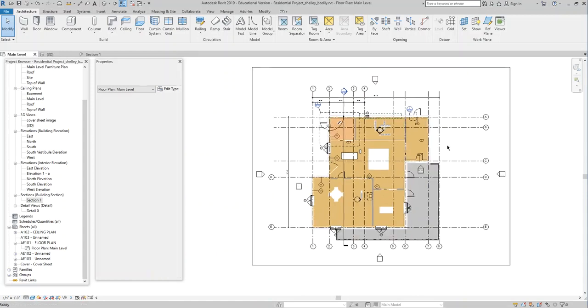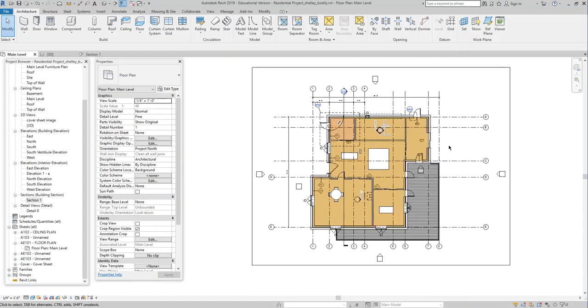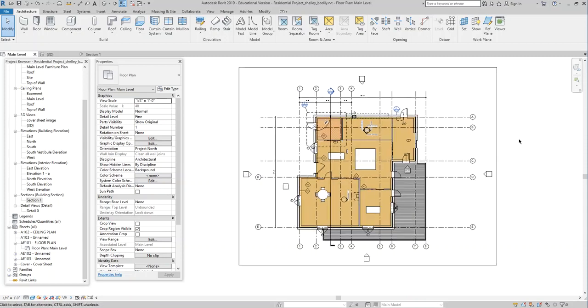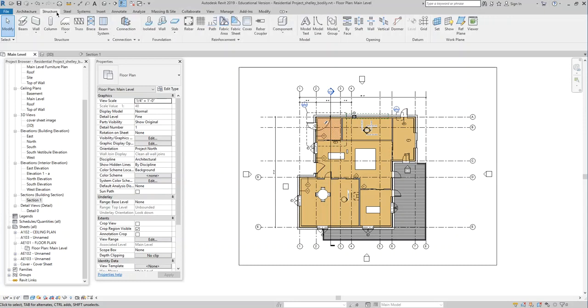But before I start generating both of those, I want to define a foundation wall and a footing in Revit, because you may go into an office or whatever and learn from somebody else. When you look at the Revit interface and you go down to Structure, you may or may not have noticed that there is a Foundation Wall and a Foundation Footing tool here, okay?